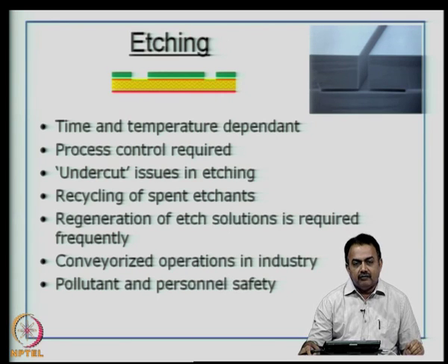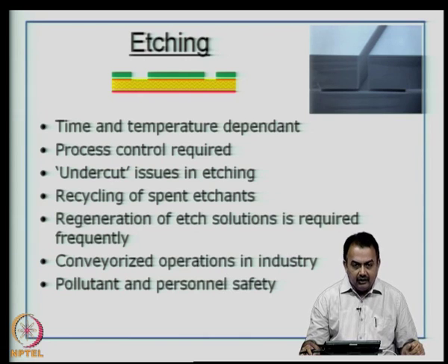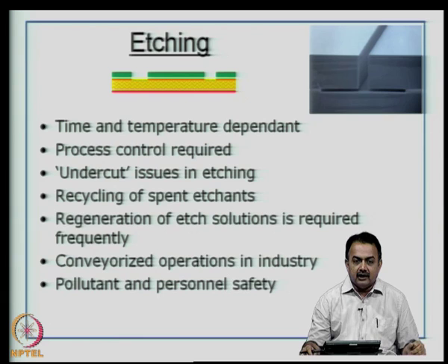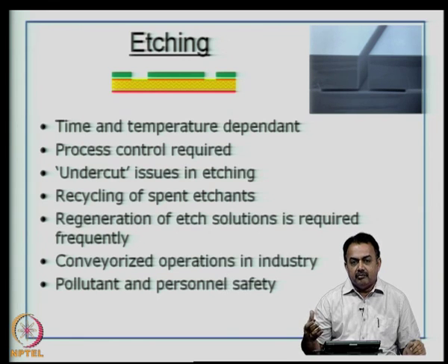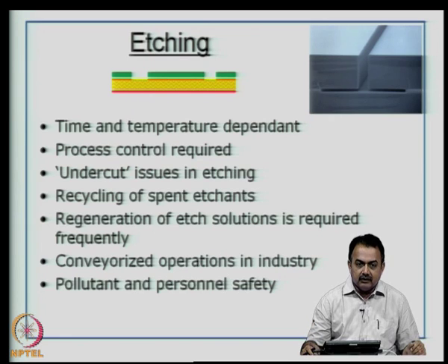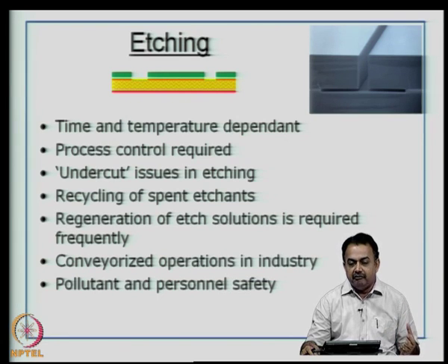Now, the environmental question of recycling of spent etchants is not normally well considered, but if you look at the current legislations on the usage of certain chemicals and also the local environmental regulatory body, they will issue guidelines on how you have to recycle your spent etchant. But today it is somewhat straightforward. That means, if you buy an etchant from a company A, the company A is willing to take back your spent etchant at a fairly nominal price. So, in that sense, you do not have to do the recycling. The manufacturers themselves are willing to take back the spent etchant. Spent etchant means that you cannot regenerate that etchant any further.